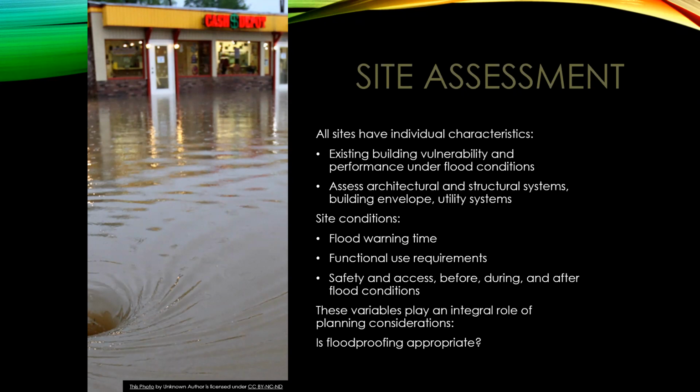repair. So in that, if we're using active measures, we have to consider the flood warning time for someone to get out there and install everything. Functional use requirements: if this structure is shut down for some time, are they going to be okay as a business? Safety and access for the active measures.